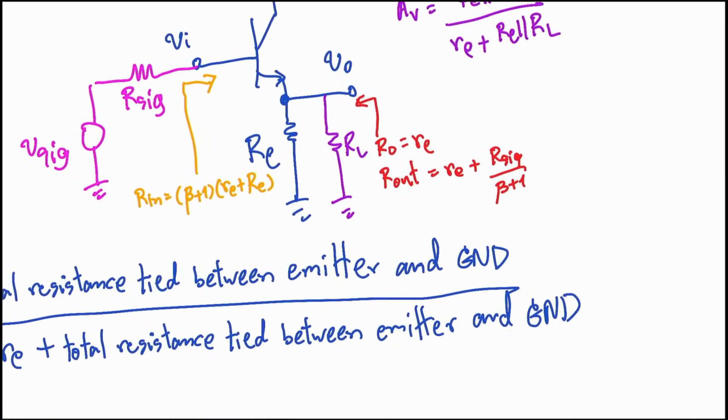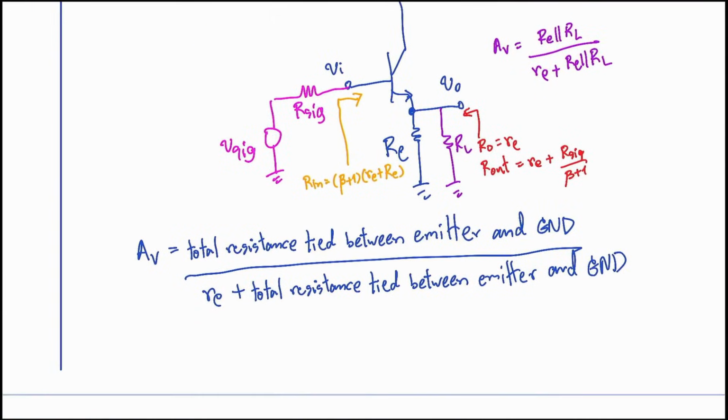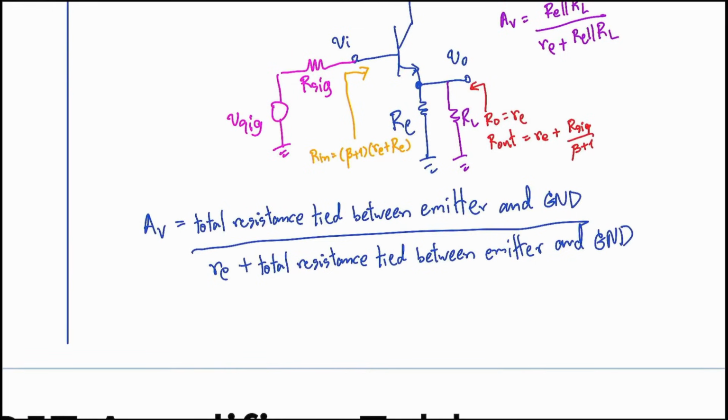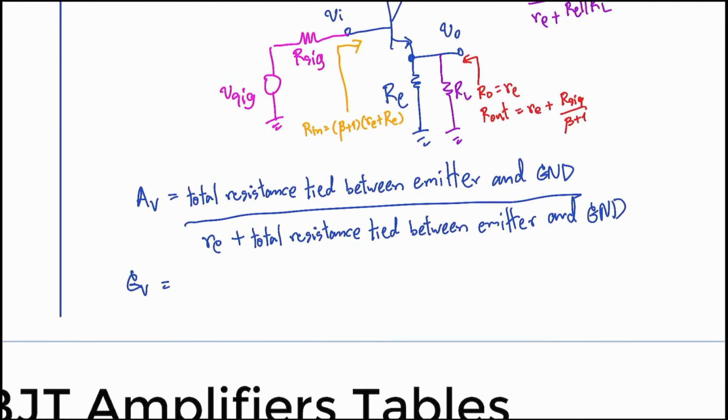If you apply the principles of the various circuit positions I mentioned earlier, you might be wondering about the actual gain, the overall gain, right? As I have said before, I usually remember the formula like this: R input divided by the sum of R input plus R signal, all multiplied by the intrinsic gain.